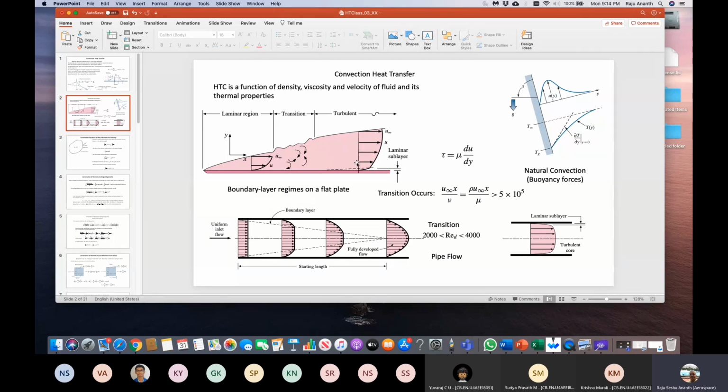Okay, so if I want to calculate, just like the heat transfer coefficient, the stress that's imparted by the flow because of viscosity at the surface, again there's a similar term. The stress is given by mu du/dy. Remember, earlier we used k as conductivity to get the heat transfer. So there is some similarity between the fluid stress and heat transfer at the surface, at least.